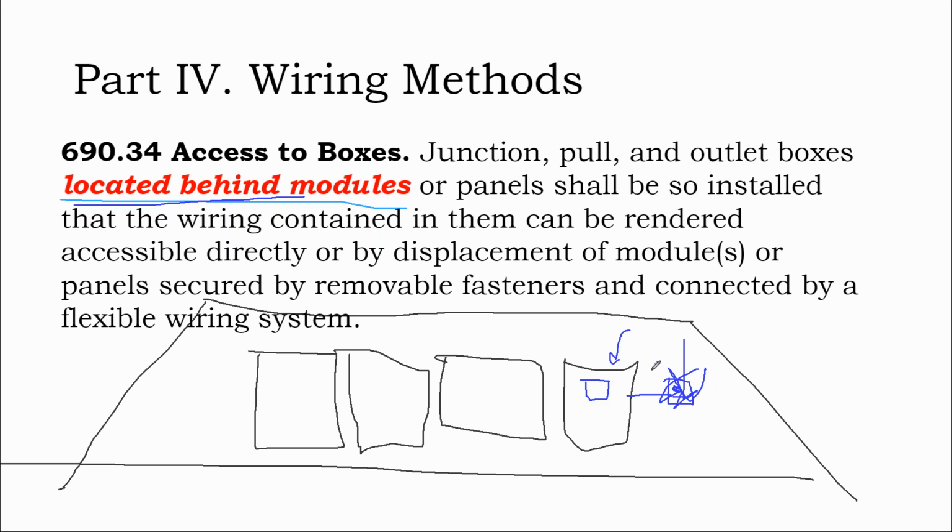And it's a matter of professionalism whether you do this or not, because a low profile box that fits underneath the solar array is a specialty item. So only solar installers really know about something like the Soladeck box. Sometimes I'll get a Soladeck box that's just an empty shell and run all the way back to the inverter. If I'm using MC cable, I'll use that Soladeck box to transition from MC to the PV wire up on the rooftop. But I love hiding them underneath the solar array because then you can't see it.